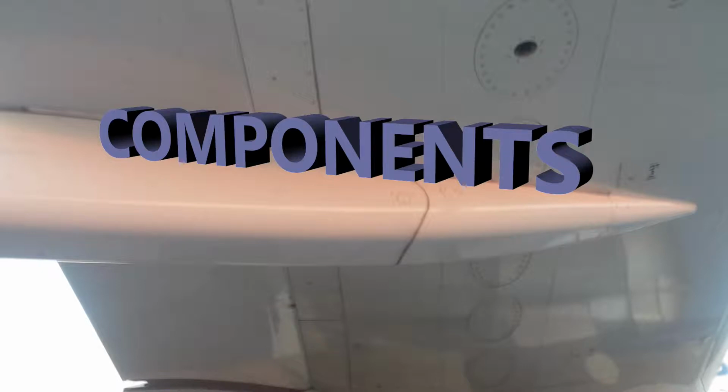Okay, now as far as your indications, for the fuel quantity indications for the center tank and both wings, inner and outer cells, if accuracy is below 3%, you get double amber dashes. So that's going to be double amber dashes on the last 2 digits. It's also going to show fuel temperature in Celsius. That's normally green, with a pulse green, and then it changes to amber if there's a problem, so if it has gone outside its range.